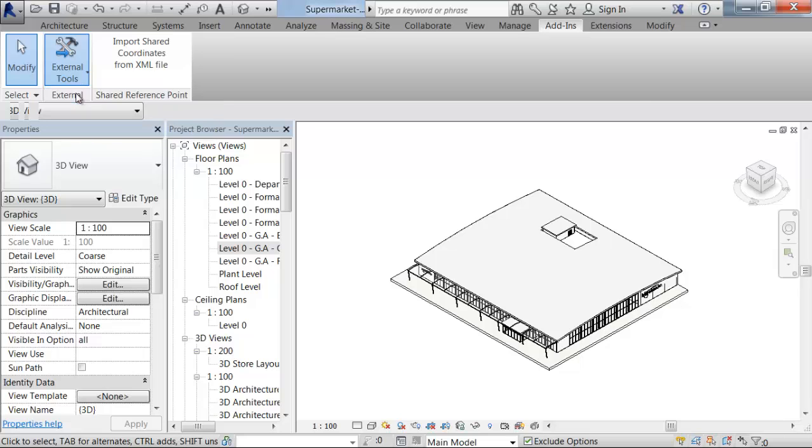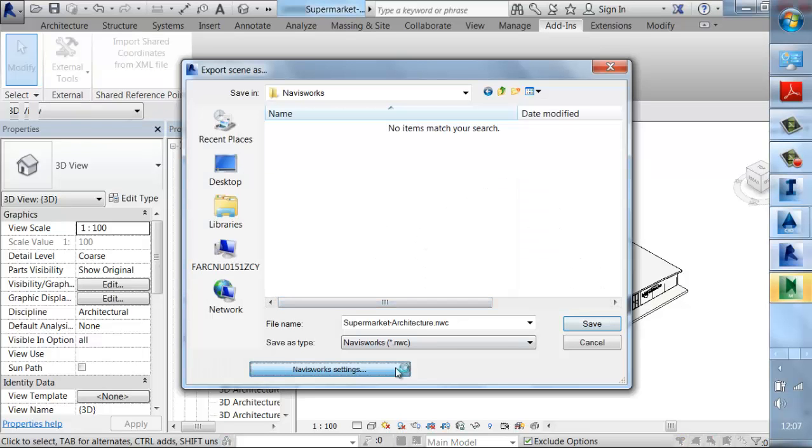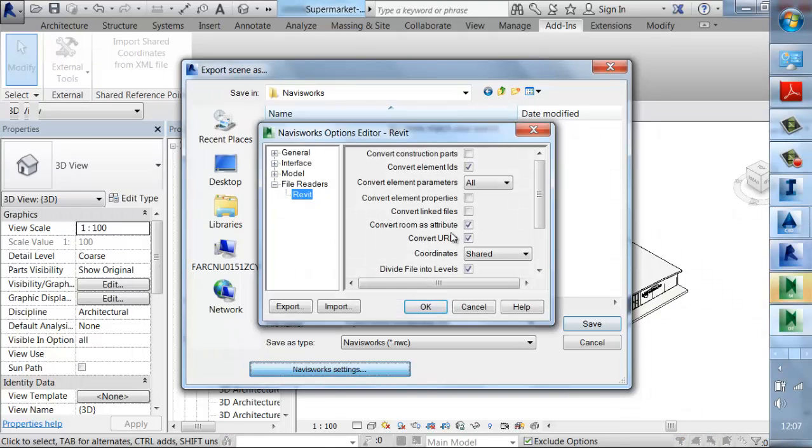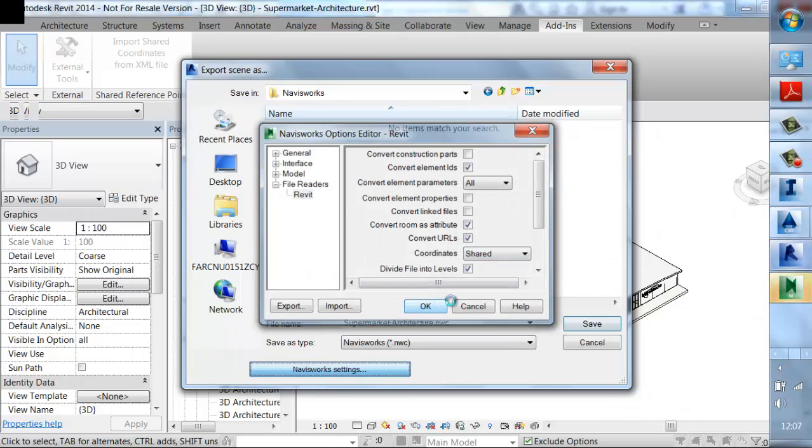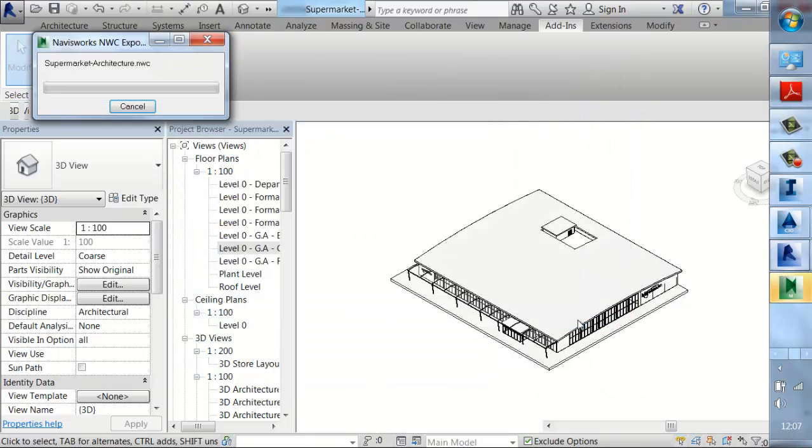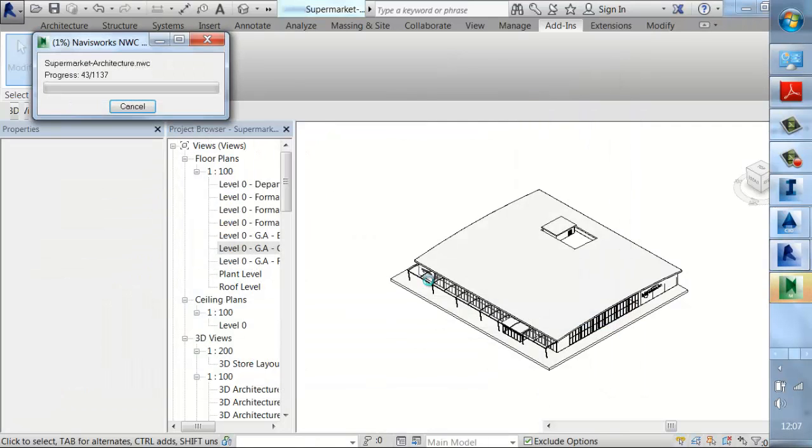So back in Revit here, what we also want to do is take this through to Navisworks. Another use here is if we want to update the model in InfraWorks, the best method to take this model in the right position is through Navisworks itself. So we're exporting here an NWC file, so it's one way of giving a lockdown version of your 3D model from Revit.